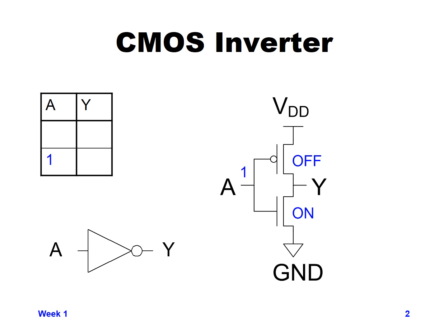But it will cause the NMOS transistor to be on. This means that our output Y is directly connected through that NMOS switch to ground, and it has no connection to VDD. So our output value of Y will be 0, ground, or a logical 0.